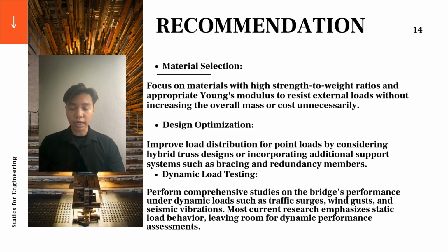Secondly, design optimization. To improve load distribution, particularly for point loads, we recommend considering hybrid truss designs that combine the strength of different truss systems. Additionally, incorporating bracing and redundancy members can enhance structural support, minimizing stress concentrations and improving overall stability.